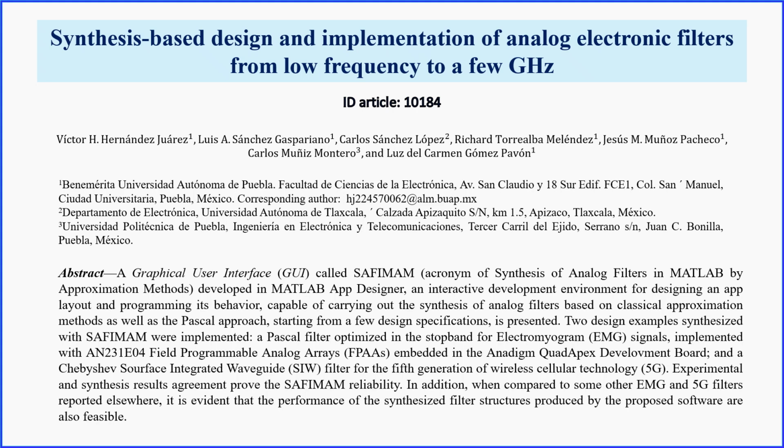alongside the Pascal approach. Based on user-defined ripple, attenuation, and transition ratio specifications, the software generates key parameters such as filter order, transfer function, frequency response, and frequency transformations. Furthermore, it synthesizes LC ladder networks in both pi and T configurations, along with their corresponding impedance transformations.